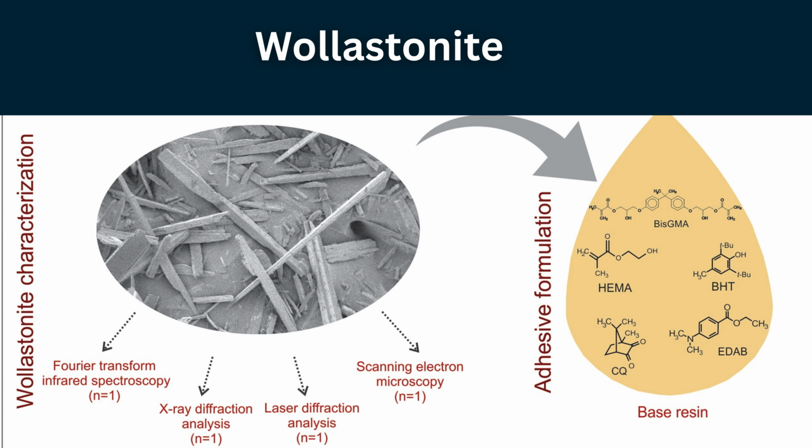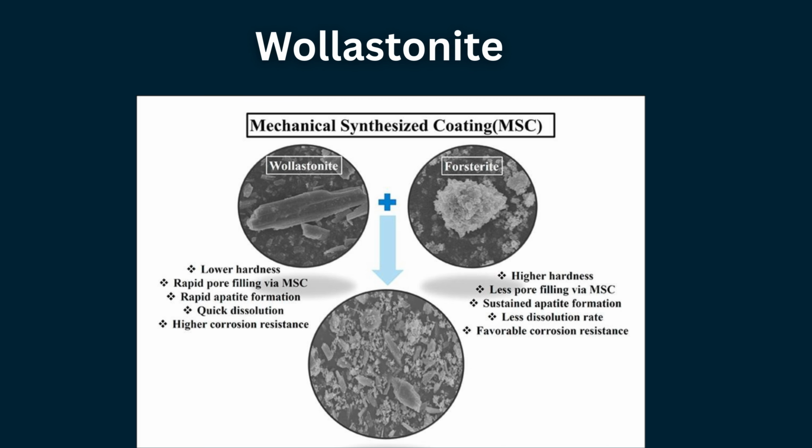Inorganic fillers. Wollastonite. Wollastonite, calcium silicate, is a biocompatible filler commonly used in dental materials. It exhibits favorable mechanical properties and low shrinkage. Because it contains calcium ions, wollastonite can release Ca2+, promoting mineral precipitation and collagen remineralization at the dentin interface. This process stimulates apatite formation and enhances bond durability. In photocurable dental adhesives containing approximately 2 wt% wollastonite, ultimate tensile strength increases from about 34.9 MPa to 46.0 MPa. The filler typically appears as needle-like particles dispersed within the resin matrix.